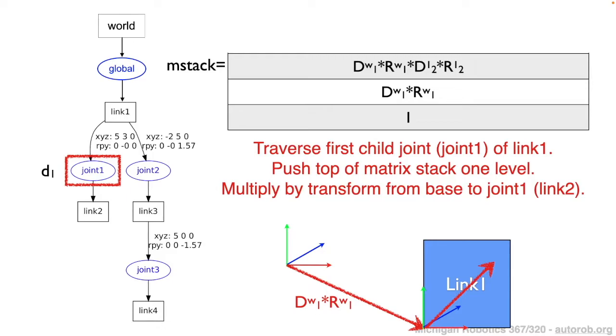And so since we assume that joint 1's origin overlaps with its child origin, link 2, the notation on the new components at the top of our matrix stack, which is shown here with my cursor, is the rotation here and the translation here, where the subscript 2 denotes that the child of joint 1 is link 2, and the superscript of 1, shown in both of those, denotes that we're transforming with respect to the parent of this particular node, which is link 1.